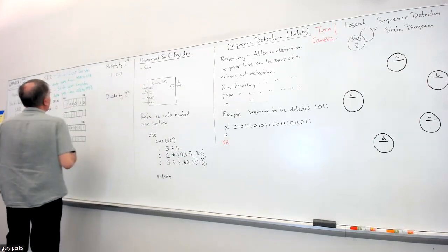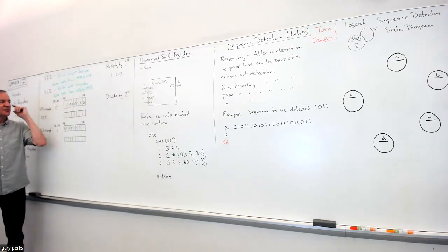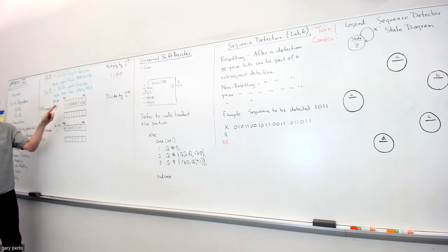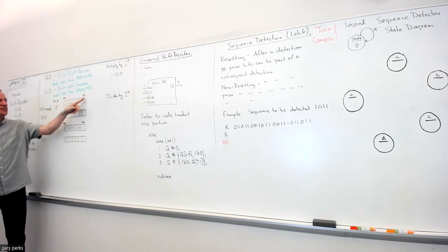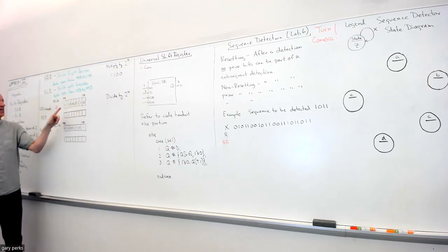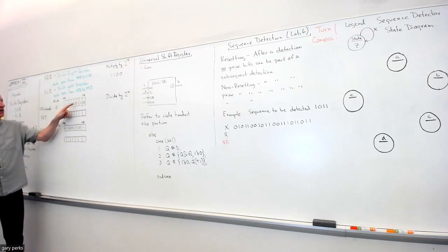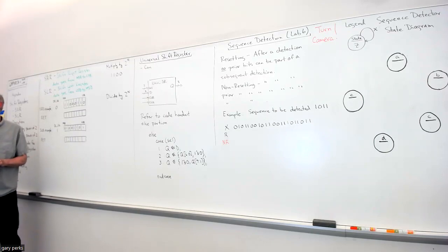Okay. Now, you haven't seen this notation before, I don't think, where there's a rectangle with some squares. This symbol is for a register. The rectangle represents a register, and each square represents a flip-flop output contained within that register, right? Because as we talked about, registers are just multiple flip-flops. So you see 1, 2, 3, 4, 5, 6, 7, 8. This is an 8-bit register, so that means there are 8 flip-flops. And inside each square, we're showing the output of an individual flip-flop.